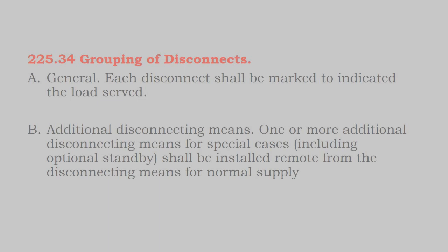And so you can't just have 3 microinverter circuits on a panel and 3 microinverter circuits on a panel on the other side of the building, both coming in to lugging on to the utility meter inside the main service panel. They would have to be on their individual disconnect switches right by the main service panel, no more than 6 of them.